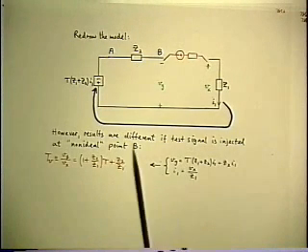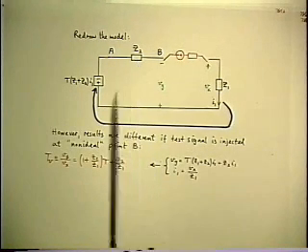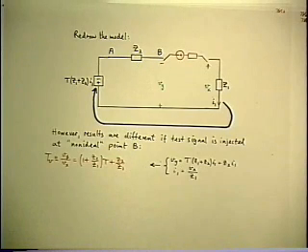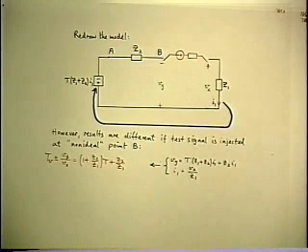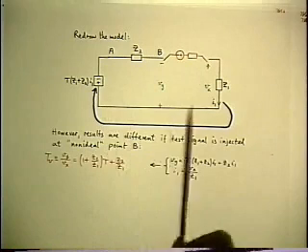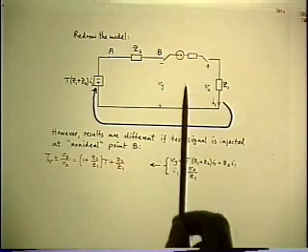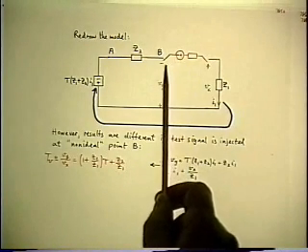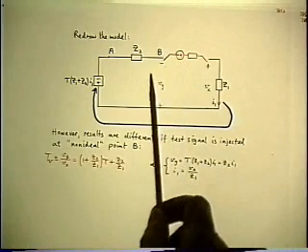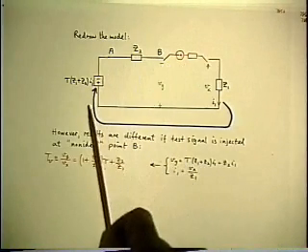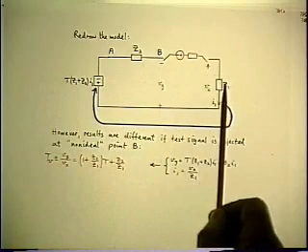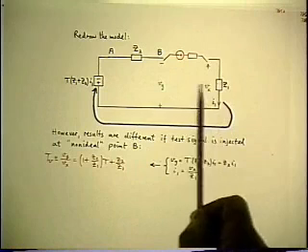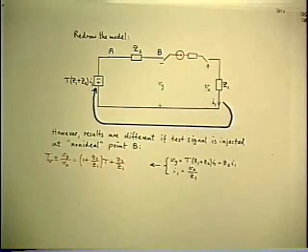And the first thing you notice is it's not the absolute value that matters, although you could have guessed that anyway. It's the ratio of Z2 to Z1 that matters, which in the interpretation of that is, when you're searching for an injection point, what you have to check is the ratio of the output impedance of the source looking back into the loop from the injection point to the impedance looking into the loop the other way.